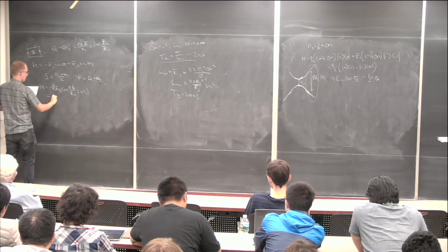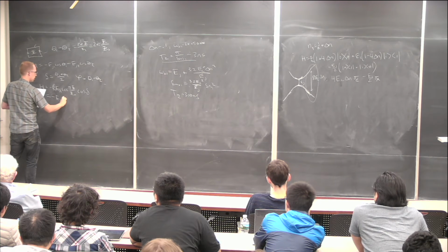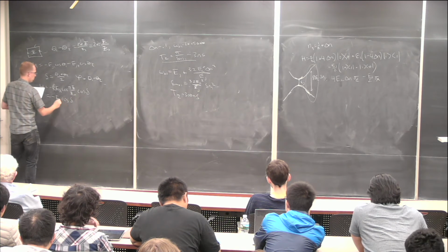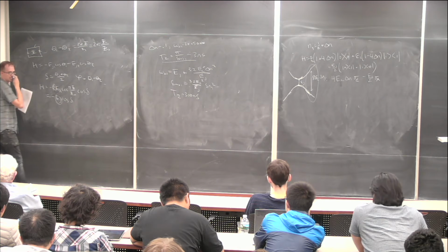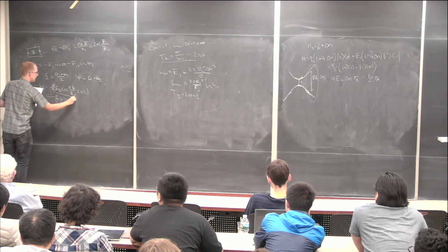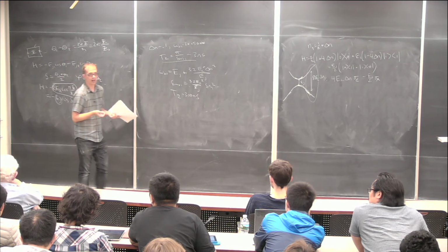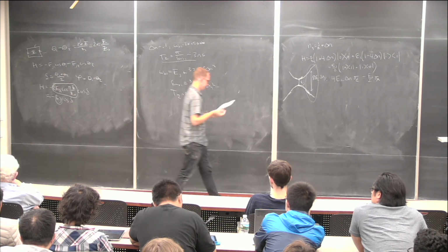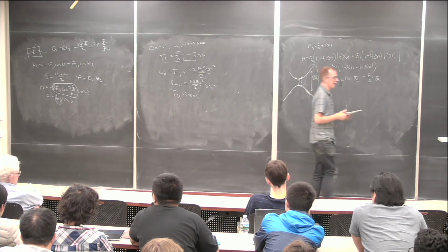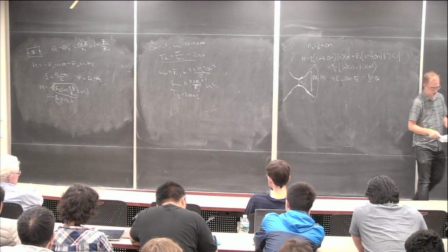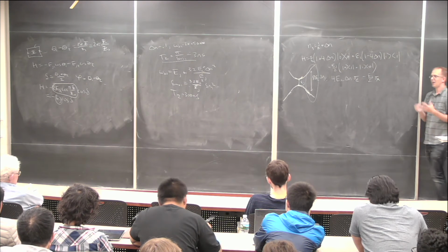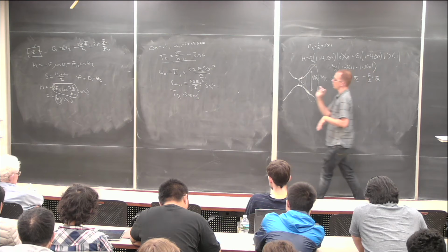And we can call that minus EJ cosine delta, where this EJ is exactly like a Josephson energy, except it can be tuned with an externally applied magnetic flux. And so now, we have good news and bad news. The good news is now we have, again, a tunable device. We can tune it now not with a charge, but with a flux.